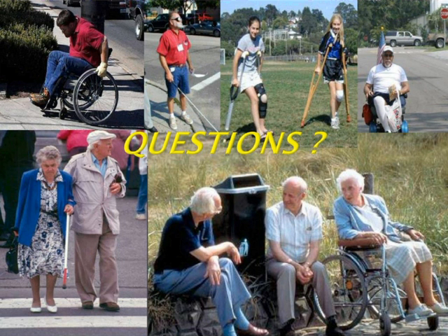There's really no spec as to what tools you use to measure. The question I usually get about levels is, for 4 feet, will they use a 2-foot level or a 4-foot level. Federal Highway here used to carry a 2-foot level around, but they caught a lot of guff from our technicians because they carry the 6-foot and the 4-foot. I guess what I have to say about that is that either one you use, if you put it on a surface and you see daylight underneath it, it's not taking a very good reading. So as long as you can show that it is on a flat surface anywhere you move it around on the ramp, either one should work. Again, there is no requirement or any kind of standard or spec as to what tool to use that I know of.